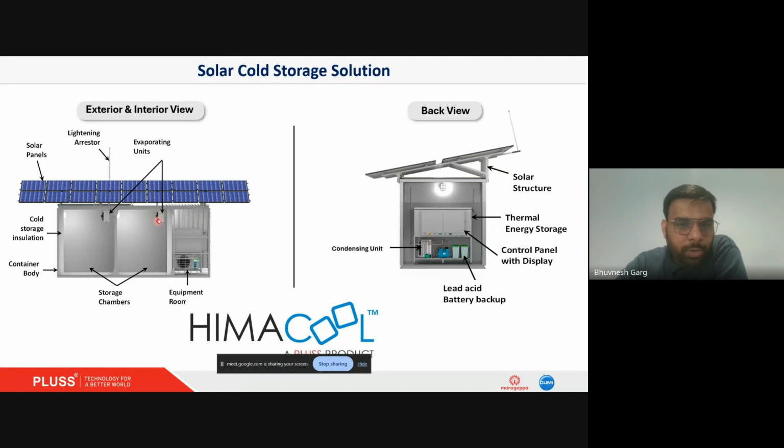These are indoor units basically, having a fan coil unit, where there is a fan running and blowing air over the coils, and through the coil there is water running, which gives energy to your cold room. There is similar piping in the tank also, where the water is circulating, taking the energy from the PCM and supplying it to the indoor unit.